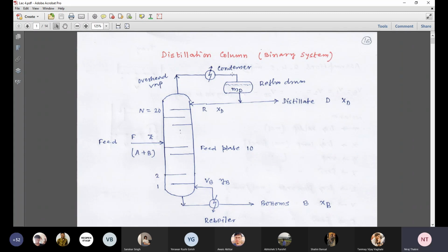This one is vapor, but this is totally liquid. After condensation, that vapor gets liquefied here, and starts accumulating in this chamber. It's nothing but a cylindrical drum. Similar to the reboiler, the liquid height gradually increases. And when the height reaches a certain level, we withdraw a portion of this accumulated liquid.